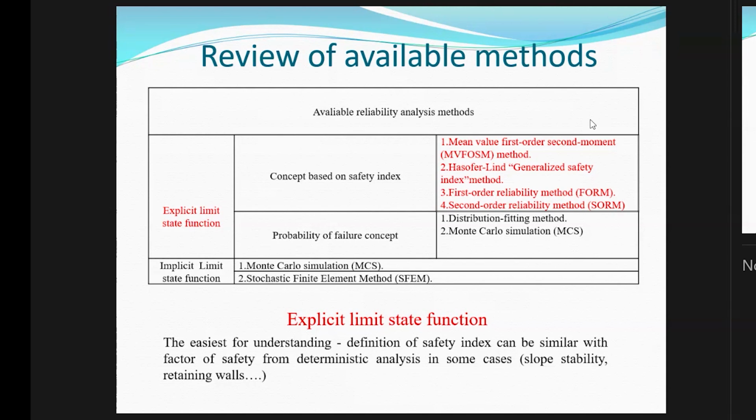Then, for example, insurance agencies or society demand that we know what the risk is, especially now in Serbia with the crashes of some public buildings. So it is very useful. For engineering purposes, you just need to fulfill the code. The minimum factor of safety is, say, 1.5, and we obtain 1.6, and we are good, we are above it. But with all these numerical values and modern technology, we are able to come one level up and speak in terms of probabilistic outcomes for our analysis.